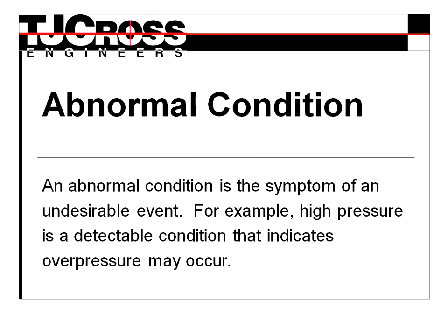All of the undesirable events that we just discussed initially present themselves as an abnormal condition. By properly reacting to abnormal conditions, we can prevent undesirable events. An abnormal condition is the symptom of an undesirable event. For example, high pressure is a detectable condition that indicates overpressure may occur.